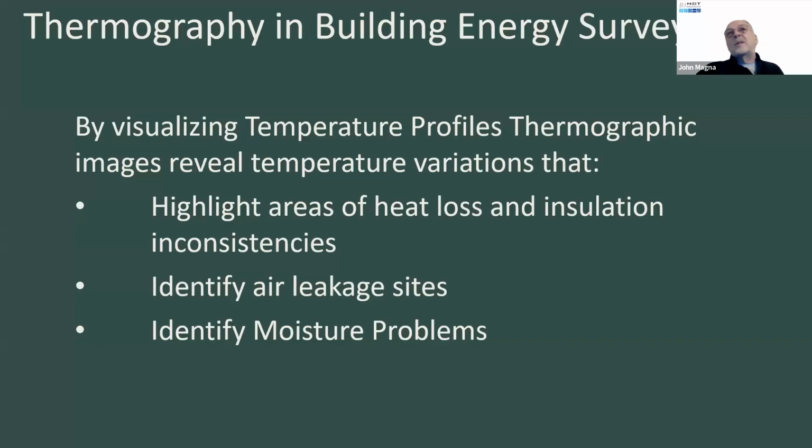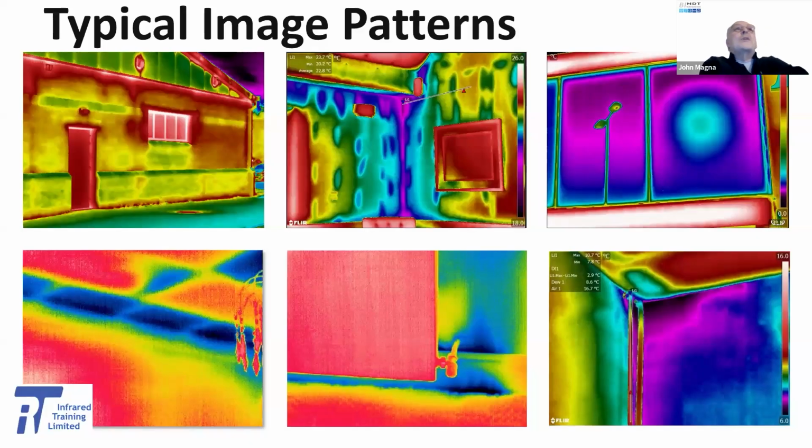Once we understand the basics of thermography, coupled with application knowledge, building performance issues are easily observable. And as with all technology, training is essential to develop good camera and survey technique. And a good grasp of construction materials and methods, coupled with an understanding of building physics, is needed to interpret infrared building images correctly by qualitative comparison, typically. So these are typical imaging patterns.